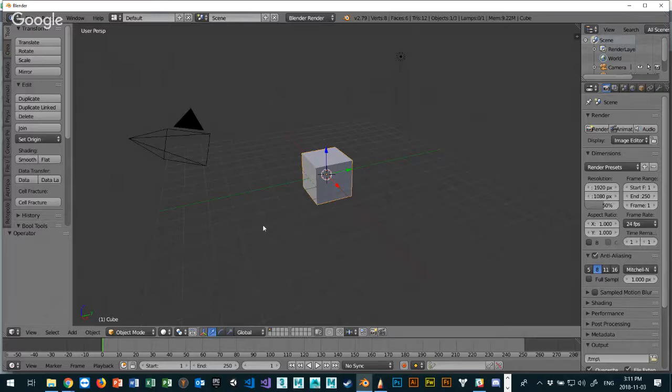So number one, one thing to do before I do anything else is, when it comes to selection of objects that you see in your 3D scene in Blender, the only way you can select objects is by right-clicking, not left-clicking. Left-clicking does not select objects. What it does actually is it moves something called the 3-dimensional cursor. Take a look here.